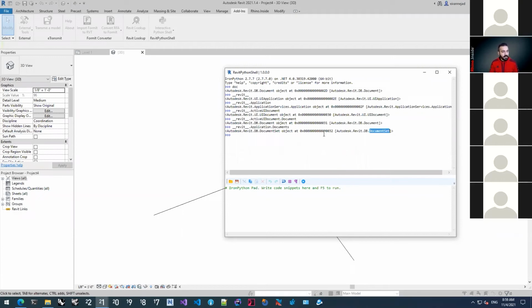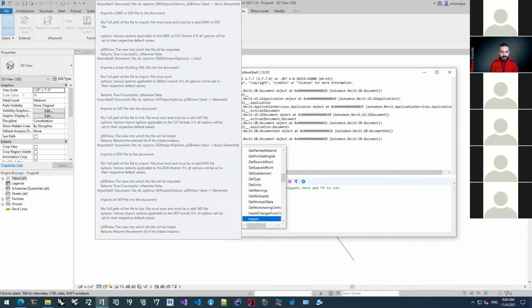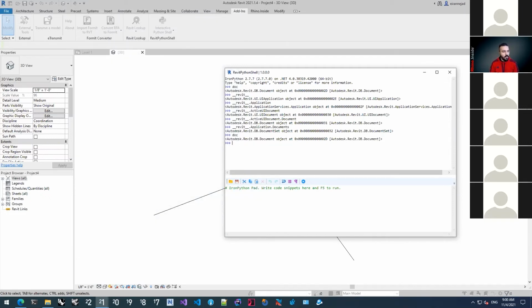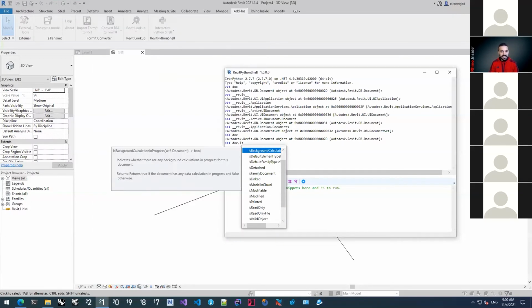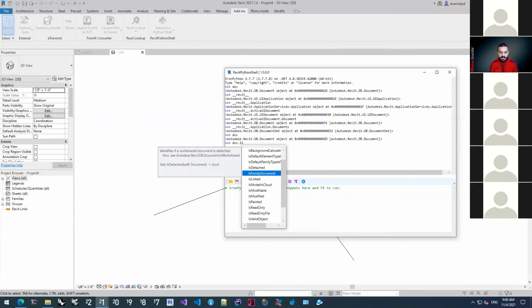And generally the way Revit works is that because they're linked in another project, you can make changes to those documents. So it is important to know what you can do with these documents. If you want to know what is available within those types, the Revit API has this convention that properties have names that start with Is. So I can say IsLinked.